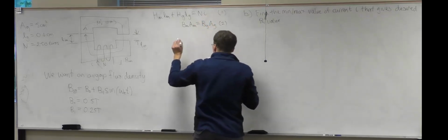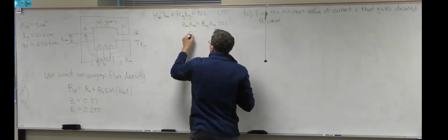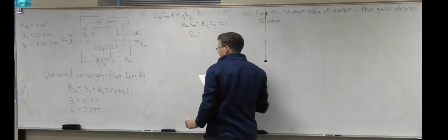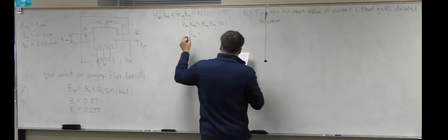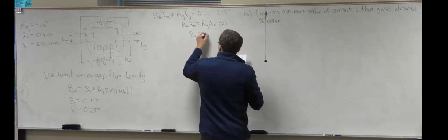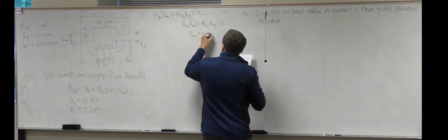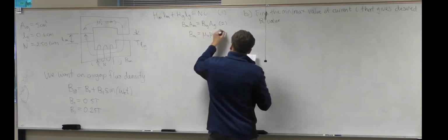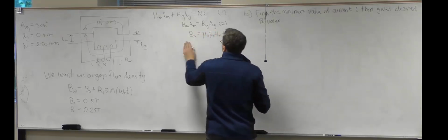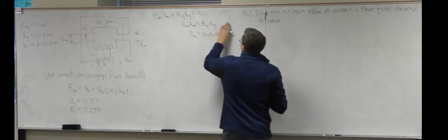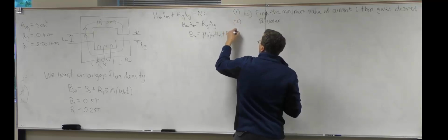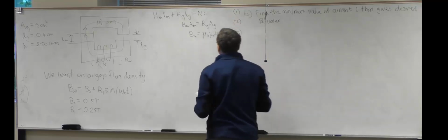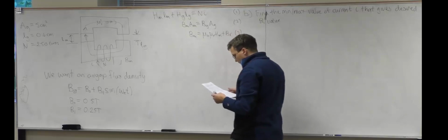And we also know that, and we'll assume we've got a hard magnetic material, and then we'll talk about that more in a minute on the BH curve. So we're going to say that it's a hard magnetic material, and so it can be modeled using this equation here that we've used before.